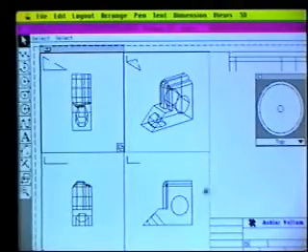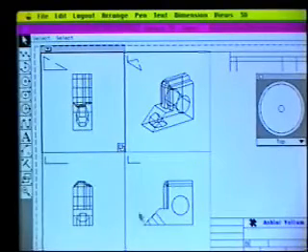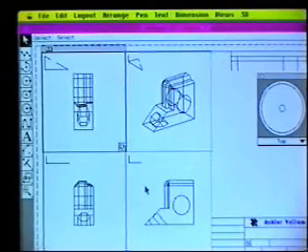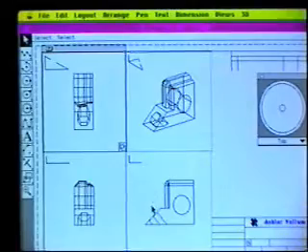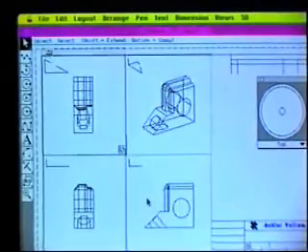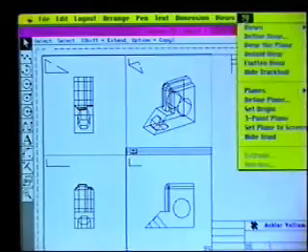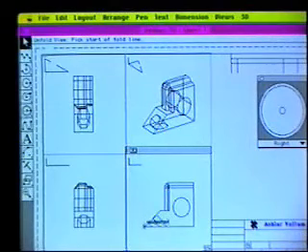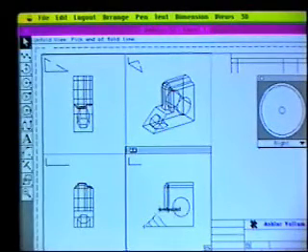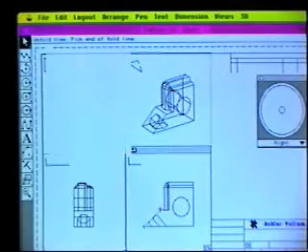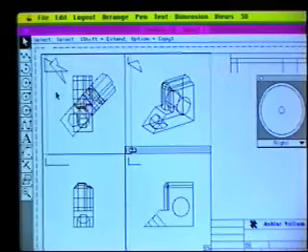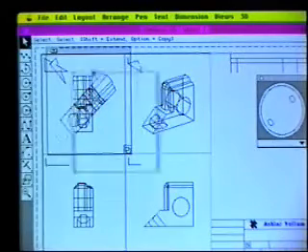How about something odd like maybe I would want a view that looks right along at this face. That's, as you would call, a projected view, one of those high school drafting nightmare problems. I would want a projected view of this sloped face. All I do is select the view and go up and say unfold view. Then I just simply go in and drag from endpoint to indicate a fold line. When I do this, another view is created. Vellum just places it, projected correctly, and puts it on top of everything else, which is actually okay because I can click on that view and move it off to the side.